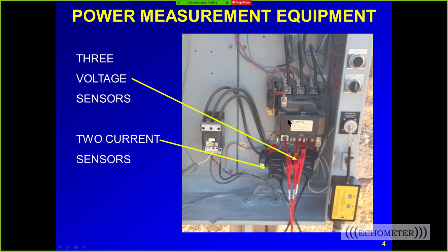So when the HOA switch is turned off, we are able to bring in the line power, and we'd see the 480 volt power, and then we would see the drop when we did a valve test, and when we turn the unit off and on, we see the sag in the voltage. You can't see it here because you're past the HOA switch, so I probably wouldn't hook it up there. I'd hook it up here above the HOA switch, so when the HOA switch is off, you'd still see the voltage up here.